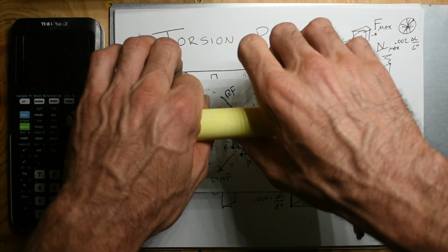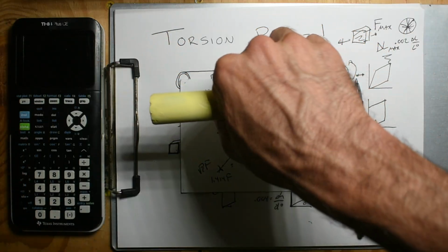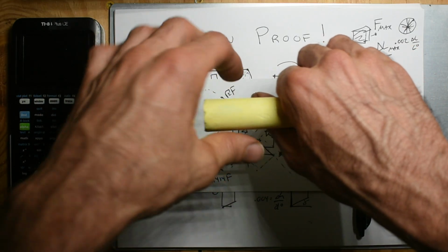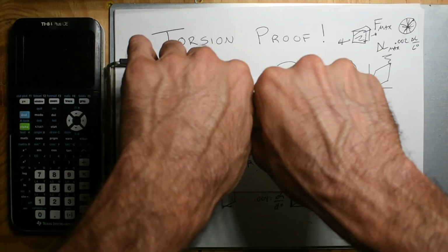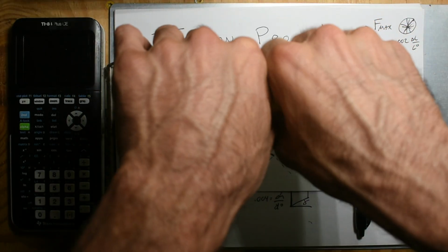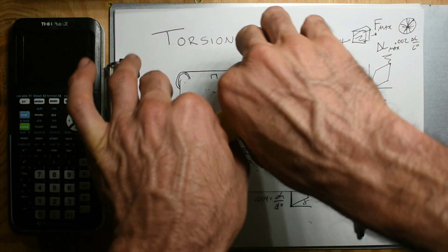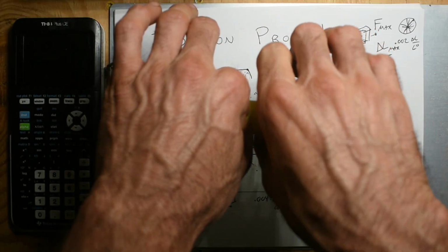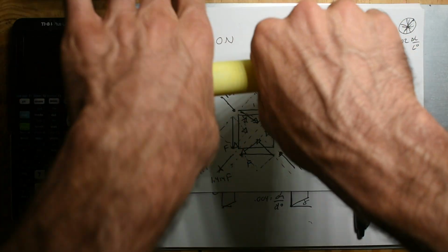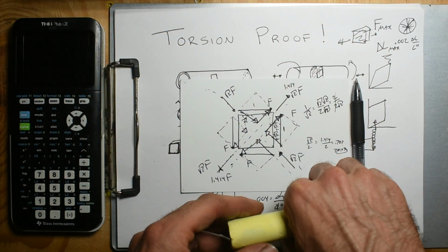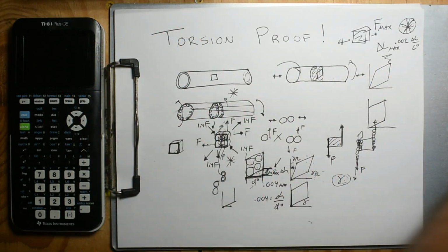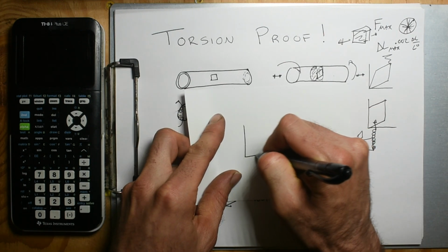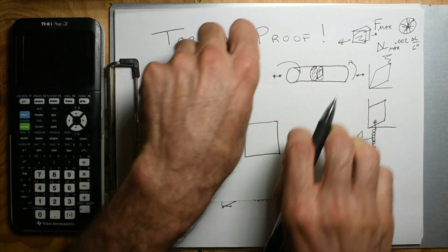And that brings it back to what we were talking about. If I just take this and put a force this way, it's just going to go that way. Nothing's going to happen. Same thing as if I grip here and do an upward force and a downward force, if that's all I do, guess what happens? Hey, look at that, it just spins. Nothing happens. So to actually get this thing to shear, I got to put an upward force, a downward force, and then let's draw a picture just so we can visually see this. Because I don't think shear is intuitive at all.